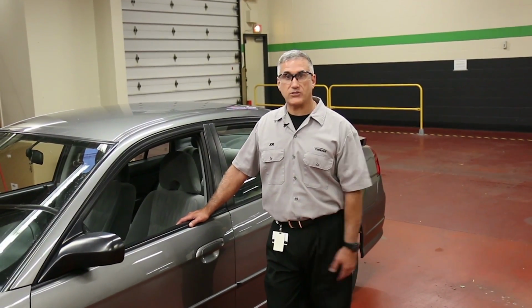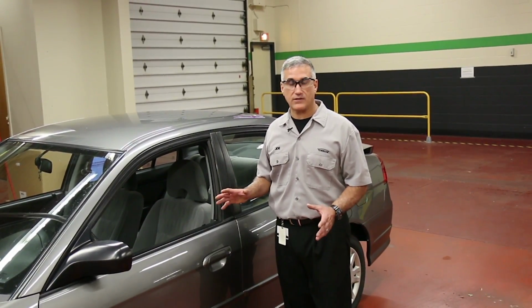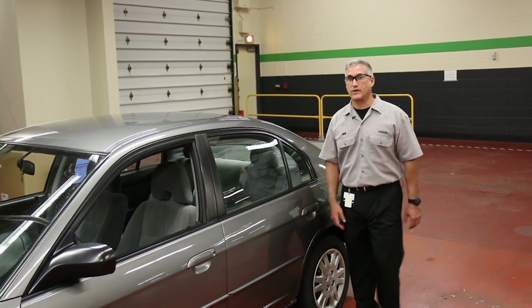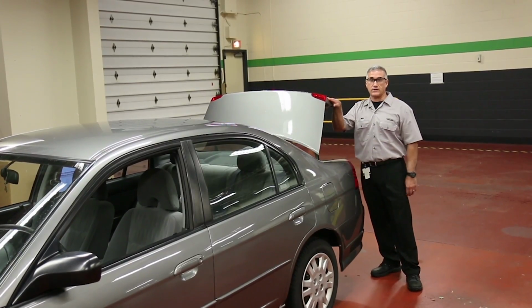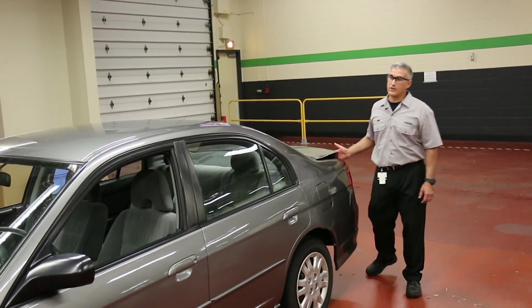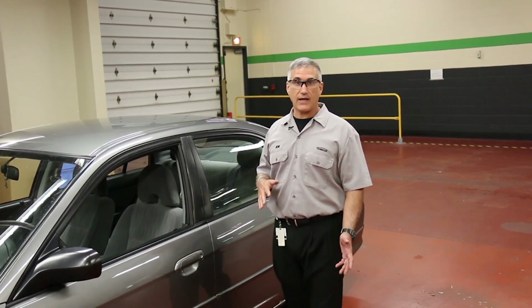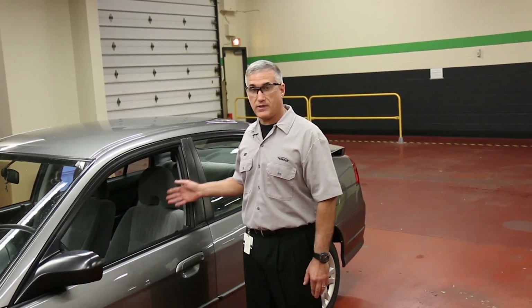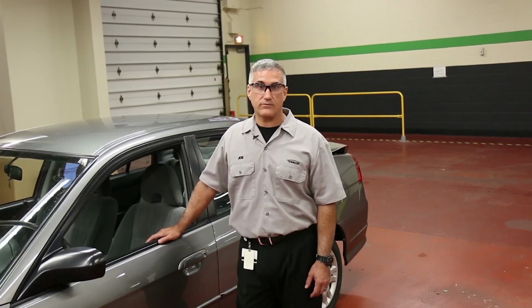You definitely want to check the tire pressure, and it's a good idea to make sure you have the same size tires all the way around. It's really nice if they're the same manufacturer of tire. You want to take a look in the trunk, make sure there's not any cargo in there that wouldn't normally be in the vehicle. You want to check the fuel level. It normally should be between 1/2 and 3/4 of a tank of fuel to get proper measurements. And you may even want to simulate the driver's weight on some lighter cars.